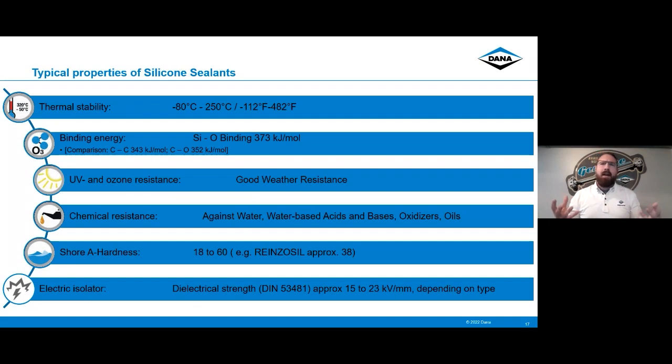And we don't think about that. We don't think about the diff cover that we just put on. And is this sealant that I used around the edge going to be able to handle very low temperatures? So something to keep in mind in that range is how it's going to keep its elasticity at -40 all the way up to 200, 210, 220, maybe a little bit more depending on your application.